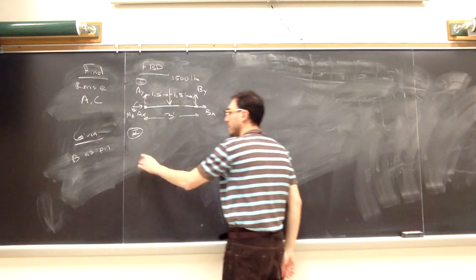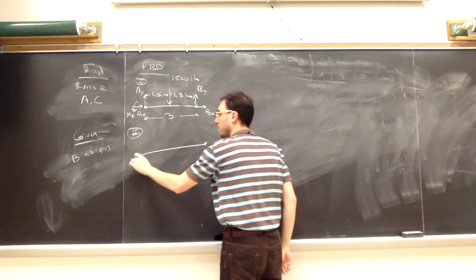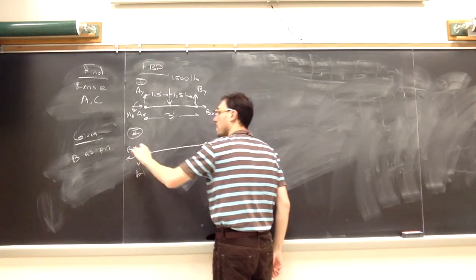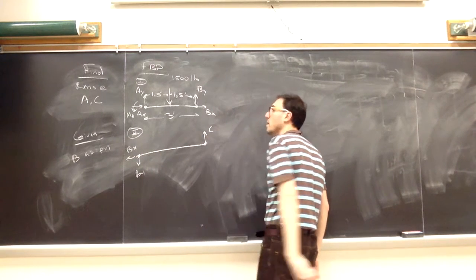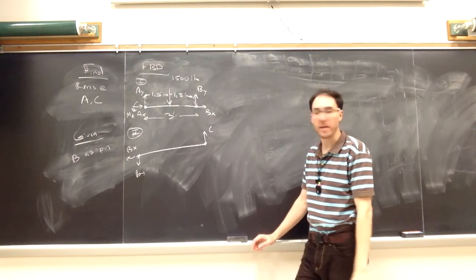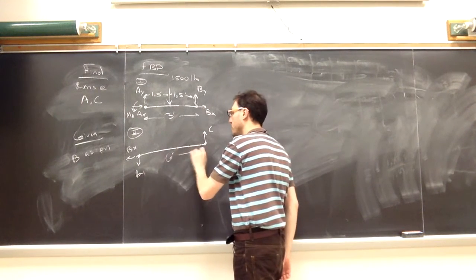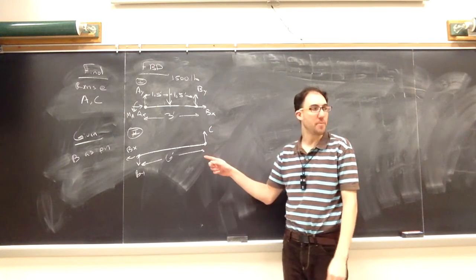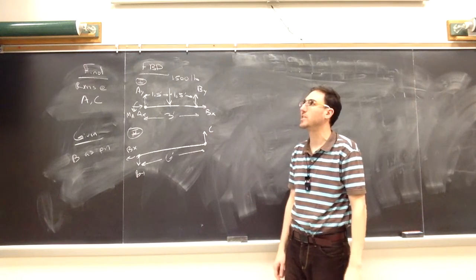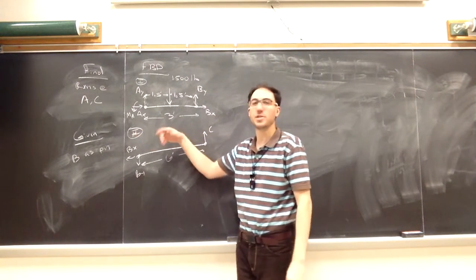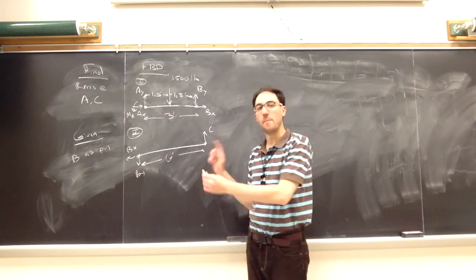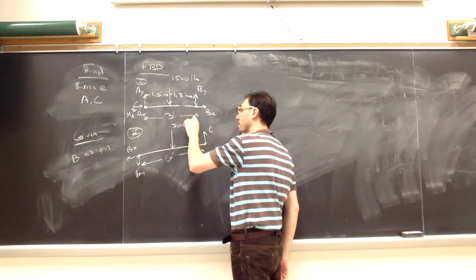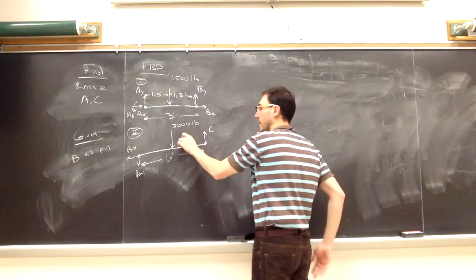My second picture, I'll go from B to C. That internal support at B, the directions are already decided for me. My support at C, I just have that vertical piece. And from B to C is a total of 6 feet. For the distributed load, just the part that touches B to C do I have to worry about. For this segment, it is uniform, 500 pounds per foot. From B to C, it acts over 6 feet. So that's going to be 3,000 pounds of load acting in the middle of BC.